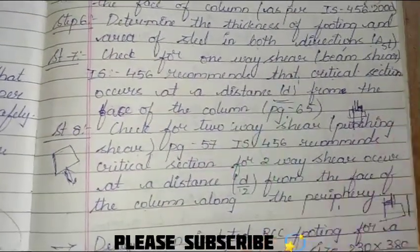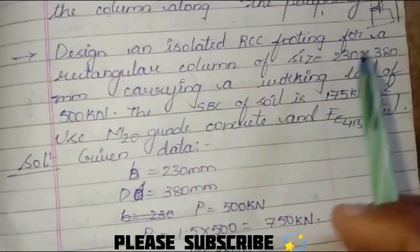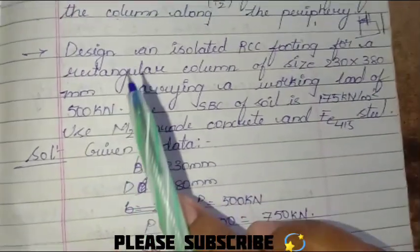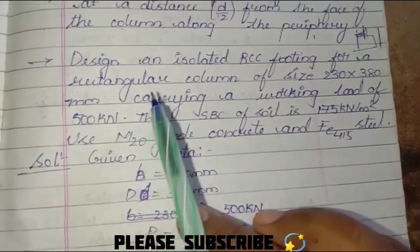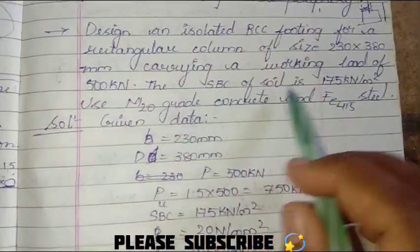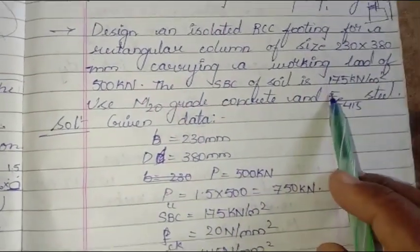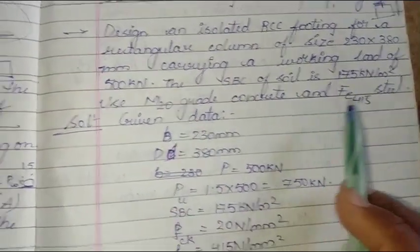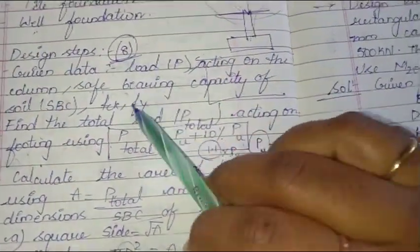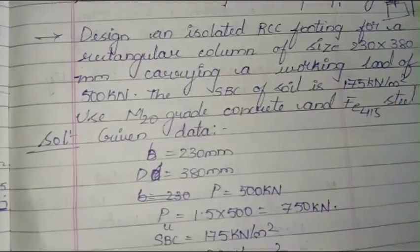Okay, so let's go to the designing part now. Design an isolated RCC footing for a rectangular column of size 230 by 380 mm. So here we are given the column dimensions, as I've already told you, carrying a working load of 500 kN. The safe bearing capacity of soil is also given, FCK, Fy. As I've told you, we'll be given the load acting, safe bearing capacity of the soil, and FCK and Fy. All these are given over here.